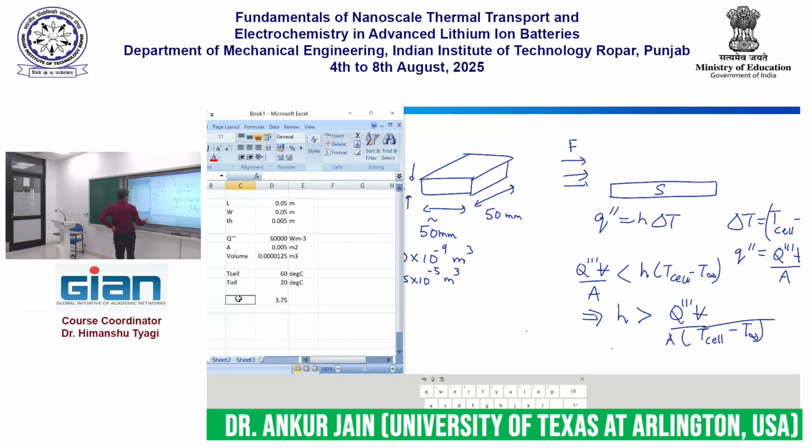So this is H, and if you remember from the lecture, the units of H are watt per meter square Kelvin. So this very simple calculation tells us that you really need a convective heat transfer coefficient of about 4 watt per meter square per Kelvin. Have we got it all right? I think we have. This looks quite fine.